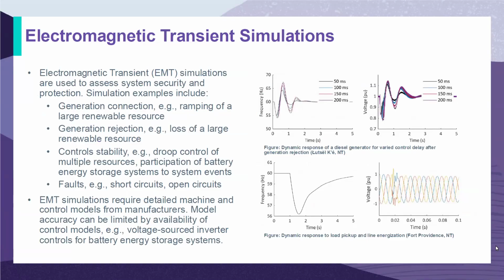And then finally, when we look at the minute-by-minute simulations of our load flows, we could say the diesel generator has this much up reserve, this much down reserve, here are the different characteristics. But then we go into more detail of the electromagnetic transient simulations, modeling the governor, modeling the automatic voltage regulator, modeling the PID controllers that are in the system.